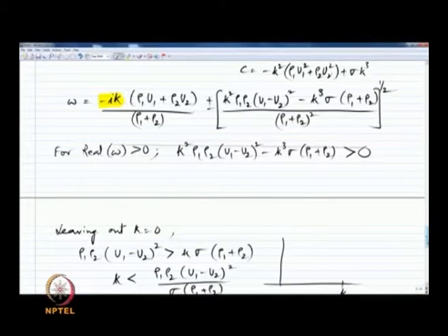Okay, so, let us go back to this earlier form just to see what it looks like. Now, a two fluid interface is the building block of all atomization systems. So, all shear induced atomizers rely on a high speed air, for example, interfacing with a generally low speed liquid stream causing atomization.